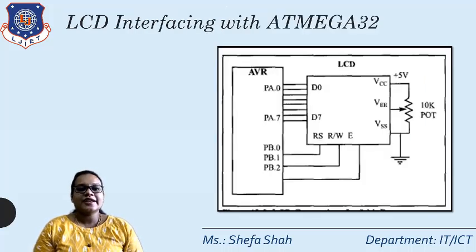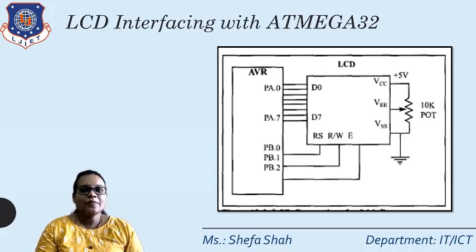Now, next, that is how to interface the LCD with ATmega32. As you can see on the screen, the LCD is connected with the AVR ATmega32. The 8-bit data which we need to transfer from the controller to the LCD is connected to port A of ATmega32. So PA0 to PA7 is connected to the 8-bit data bus of LCD, that is DB0 to DB7, that is D0 to D7.